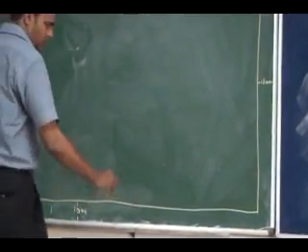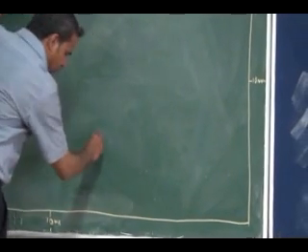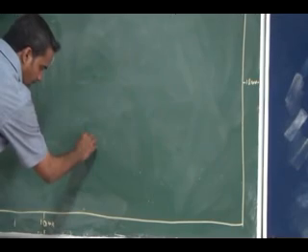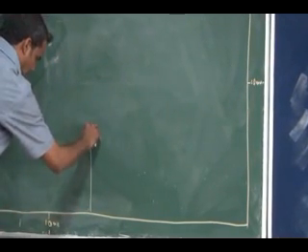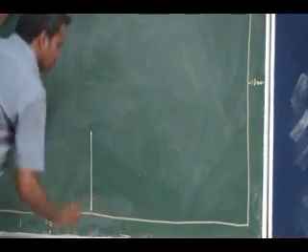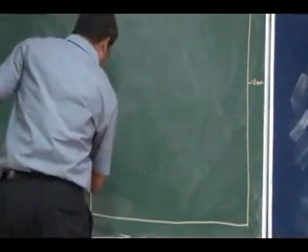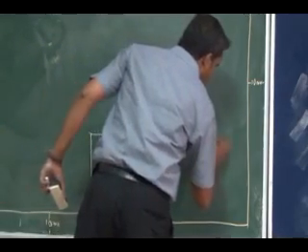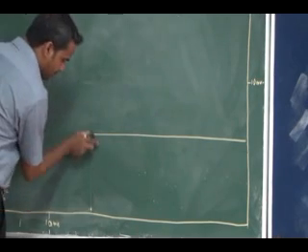The title block occupies the right bottom corner. The height of the title block is 50 mm and the length is 150 mm.